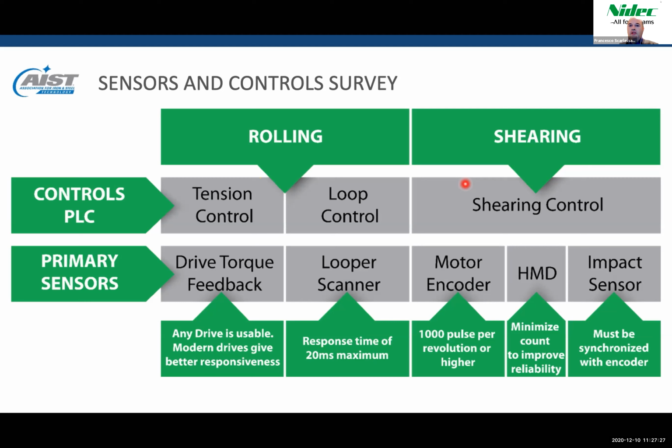And of course, there is a kind of legend in the industry that says that the speed control of a shear must be done inside the drive or using some special hardware due to the dynamics of the control. This was true when the PLC had less computational power than is available within the last 10 or 15 years. Part of the survey will be to determine the age and capability of the existing PLC to ensure that the speed control can be performed inside the PLC.